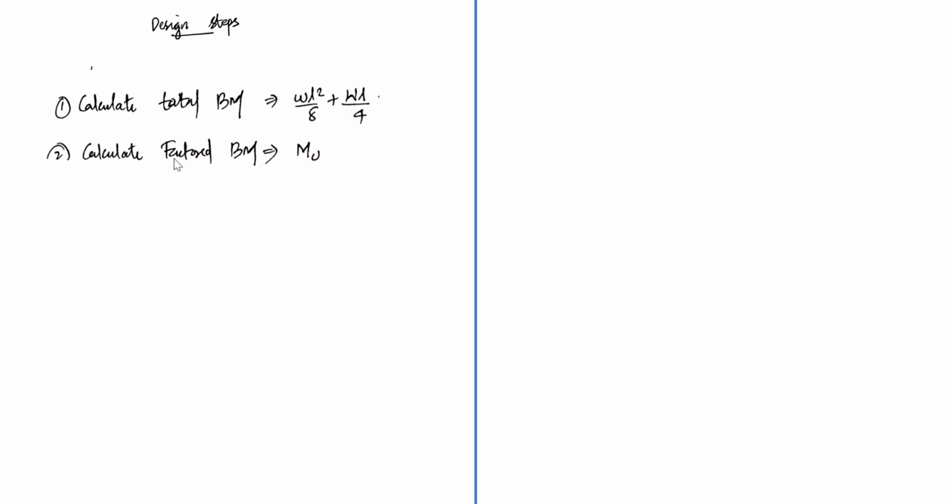Now the second step is to find the factored moment. Based on your type of loading condition, you need to find the factored moment. The factor of safety for the load should be applied to find the factored moment.